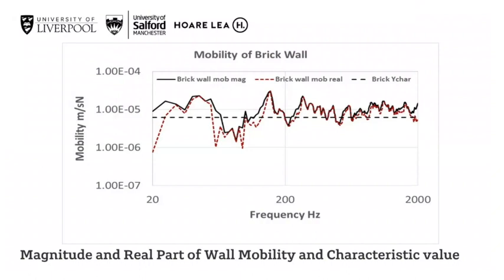And you can still see, for this kind of realistic structure as well, you are not far off by just using a characteristic mobility, especially knowing how much you may need to do if you want to go by the measurement route. The characteristic mobility of this brick wall matches quite well if you think about the average response in that frequency region. If you draw an averaged line across that mobility curve, it would match quite closely with the characteristic mobility curve.